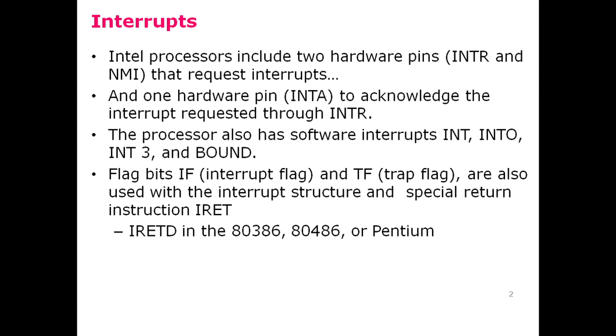It's an interrupt return that transfers the control back from the interrupt service routine, or interrupt handler, or interrupt procedure. And in the later microprocessors 80386, 80486 and Pentium, there is an interrupt return double instruction, IRETD, that returns from the procedure, but it's a double version of the IRET interrupt return instruction.